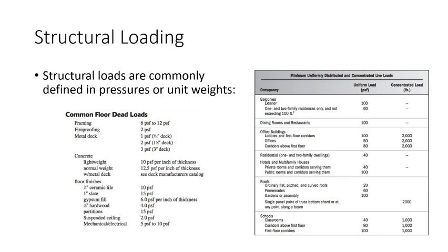I mean, what happens in February to bridge decks in West Virginia? Some snow, and what goes over the bridge? Plows. And what do plows do to the bridge deck? They erode the surface of the deck, right? So there is a sacrificial wearing surface on the top of the deck to account for wear and tear. But traffic, snow plow. So that's one of the things you'll find that's kind of interesting from state to state, is that they'll have different specified thicknesses for sacrificial wearing surfaces dependent upon the conditions.